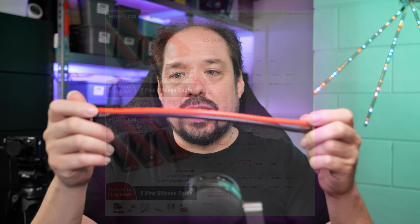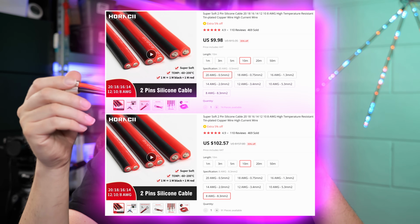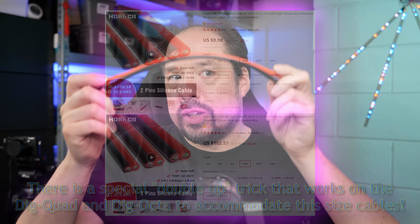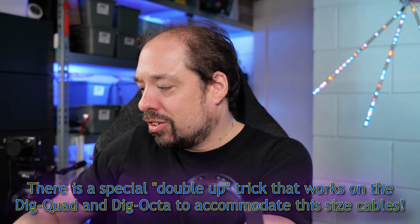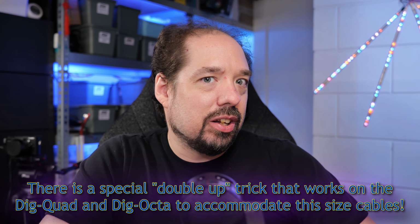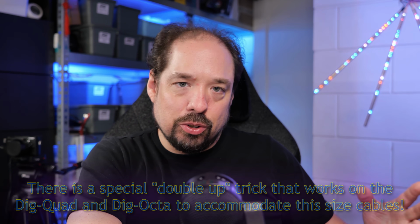Even if that by itself wouldn't be a problem, it's hella expensive. And you can't screw that into a terminal of any of the Quin LED boards, because it's just an insane diameter cable to get the little voltage drop we need to survive 16 meters for 8 amps that we need to run that LED strip.